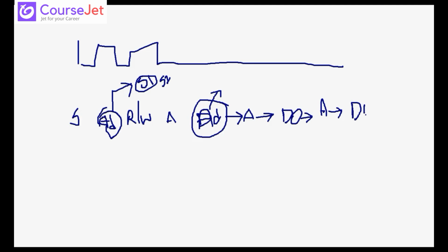Here again, once you give a particular address for D0, the next data will be stored at the next address location. If you give this address as, suppose, 000, and the data is, suppose, 73, then the next data, 75 or any value, will be automatically incremented to addresses 0, 1, 2, 3, 4. However many data you give, that many address locations it will provide or increment. This is for the write operation.